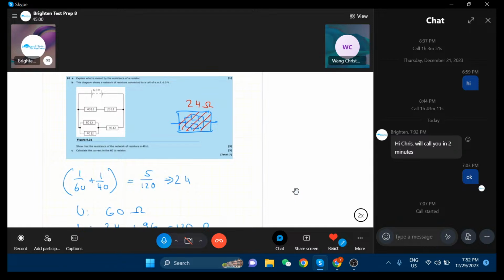So it could have been totally differently configured for whatever reason. There were two resistors in parallel, 60 and 40, and hence you get 24 out of that. And then you do the next thing, then you add it with the 96, like you did. This one is already on its own. Maybe it has been a black box as well. We don't care. So that's why we then put them together into the new black box, which then says 120, right? Yeah. So very nice.